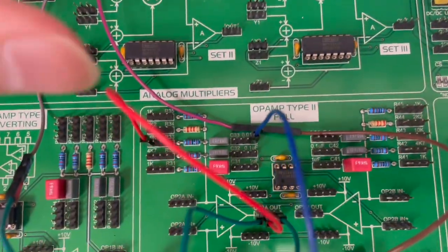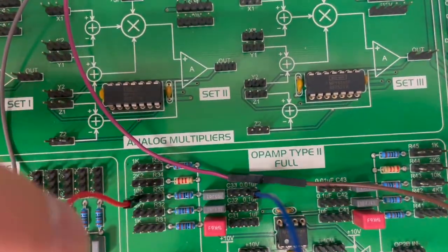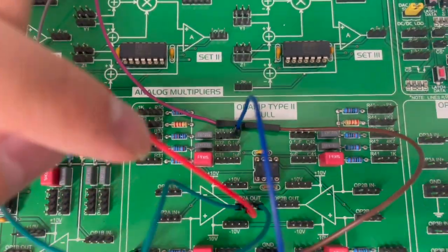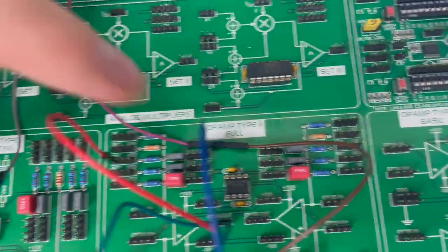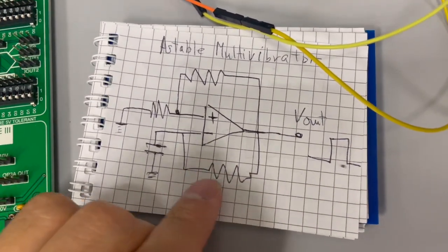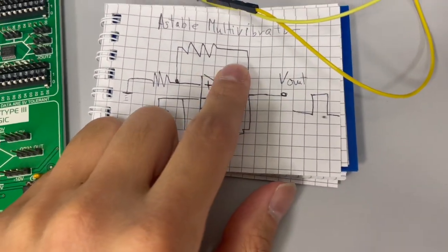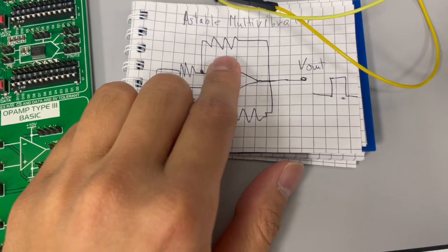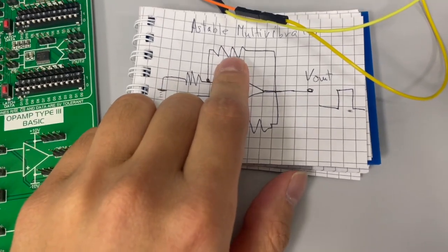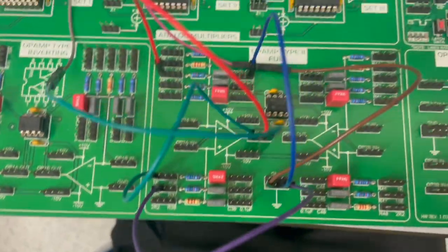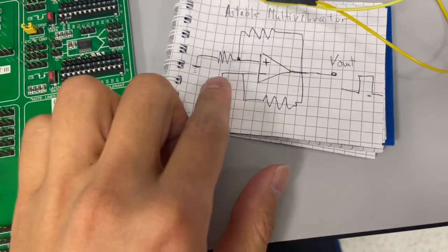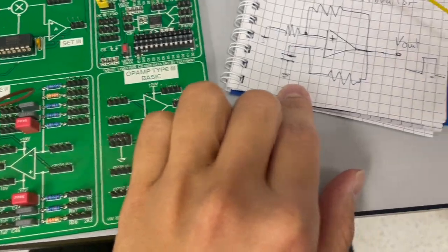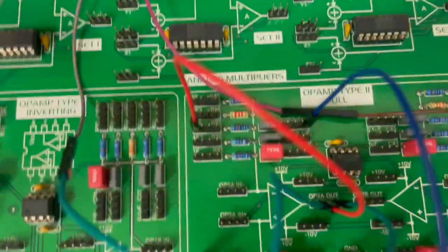For the minus connection, choose the biggest resistor we can here, 10K. So we have a feedback loop of a 10K resistor that goes from the minus to the output. As is written here, the minus goes to a resistor, and another resistor goes here. It should be 10K, but since we have a limitation of resistors here, we're gonna choose 1K and 2K, which make 10K. Also you have to connect the capacitor to the negative input.